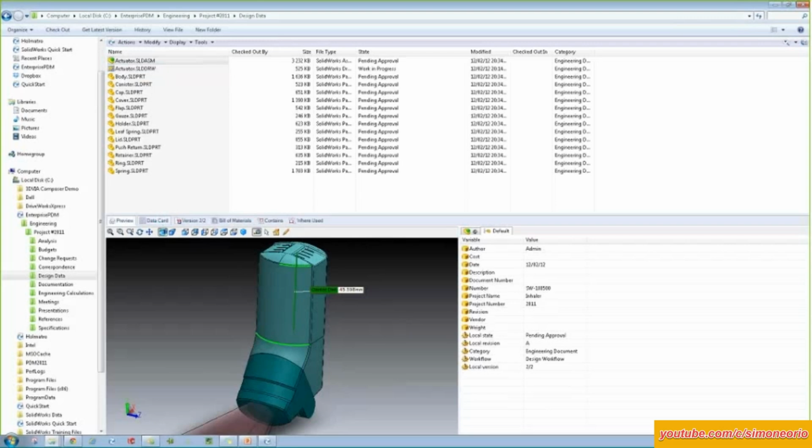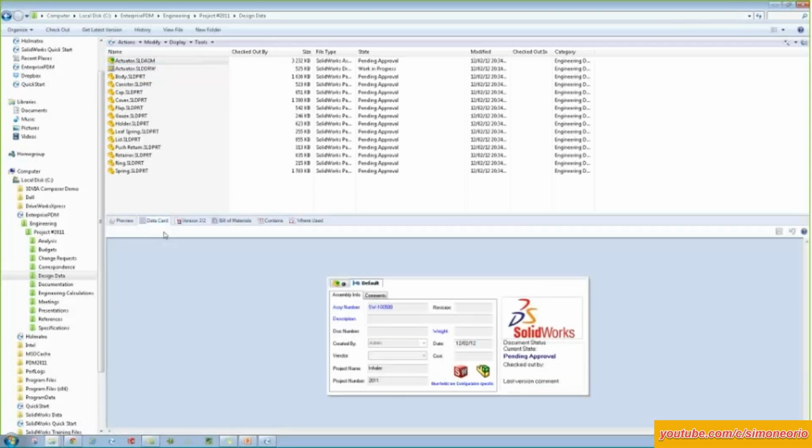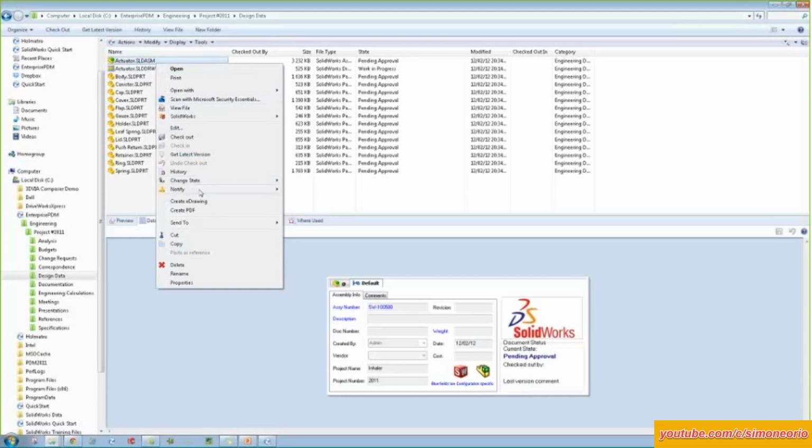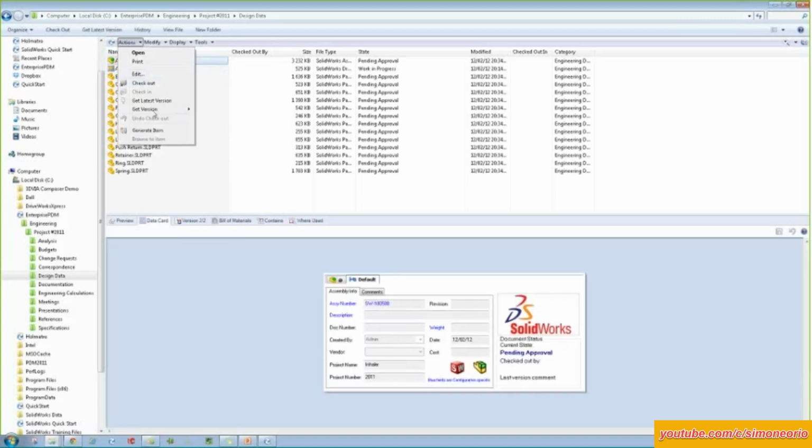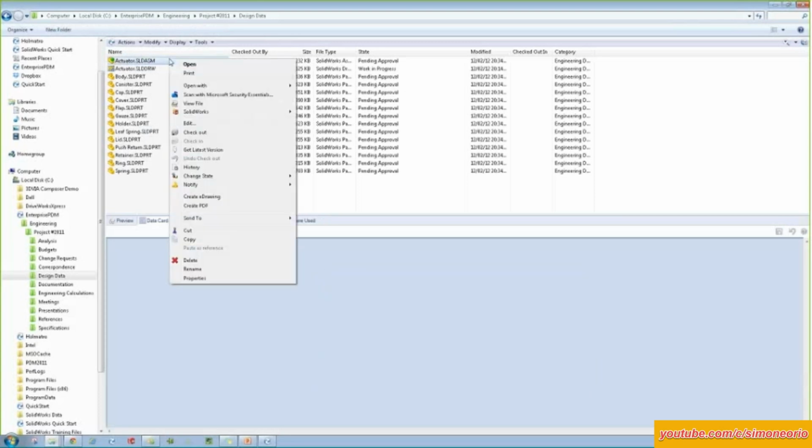Also involves data cards, so any information such as product number, customer, this is completely customizable. This card can be tracked with this product. We can go back to previous versions really easily. If I right-click on the assembly and I go to the previous version, you can see I've gone through a couple of versions here and even a revision. So my versions are numbered, so think of these as iterative and it's not quite approved yet. Once it gets approved, it goes here. Then I can right-click on it and choose Change State and choose Approved. I can go through Analysis Required or Changes Required.